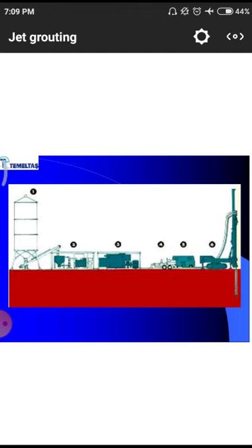The machine will simply mix all the quantities of cement plus aggregates plus the content of water plus admixtures. After this, those materials will be sent to these pressure equipments. Those pressure equipments will pump those cement jets with the help of high pressure. These machines simply flow those liquids into these holes.